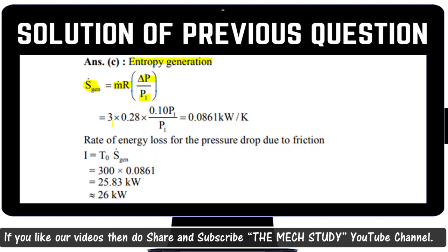M is already given as 3 kilojoule per second, 3 kg per second, sorry, and the R value they have already given, 0.287 kilojoule per kg Kelvin. All the units they have provided in kilojoule per kg Kelvin. Similarly for the pressure drop, they have given 10% with respect to the initial pressure. So P2 minus P1 is 10%, and if you put this in the formula, the P1 and P1 are going to be cancelled, and if you solve, you will get the entropy generation as 0.086 kilowatt per Kelvin, because all these data we will put in kilojoule per kg Kelvin.